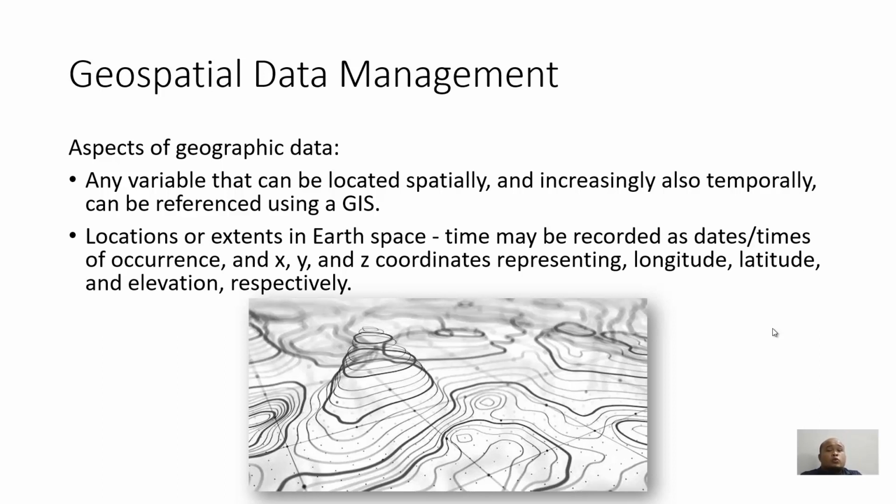So, how to explain the position? In order to explain the position of, let's say, your sampling point or the earth features, whether man-made features or natural features that you want to collect, it is represented with coordinates. The coordinates have a value of x, y, and z if they are projected coordinates, or they can have longitude, latitude, and elevation data if it is not projected, if it is a geographic representation.